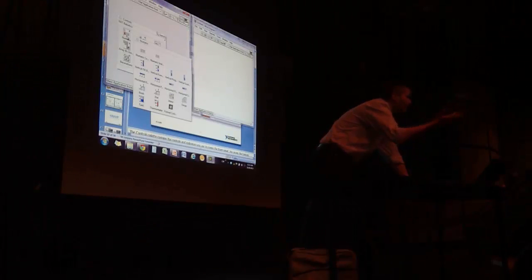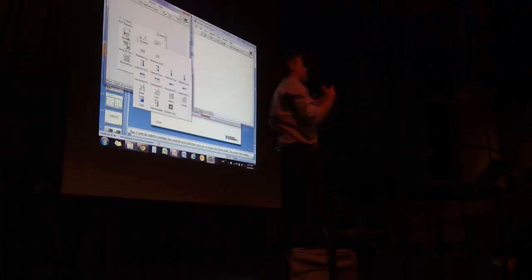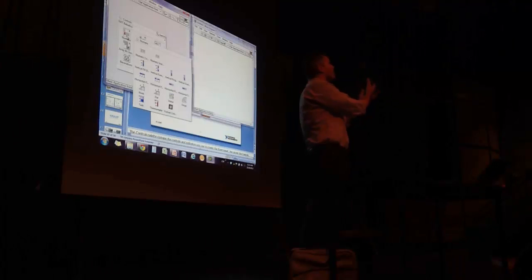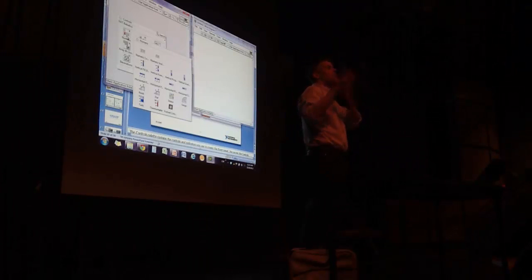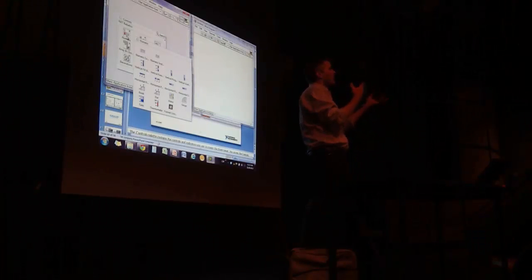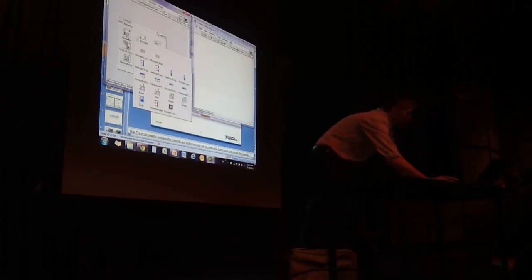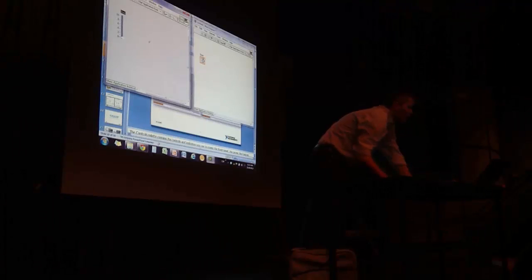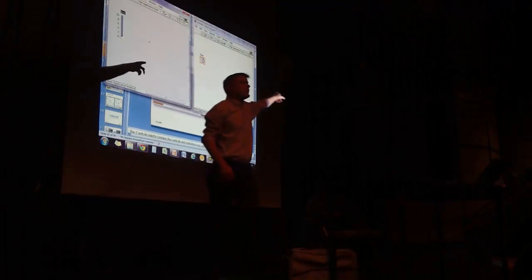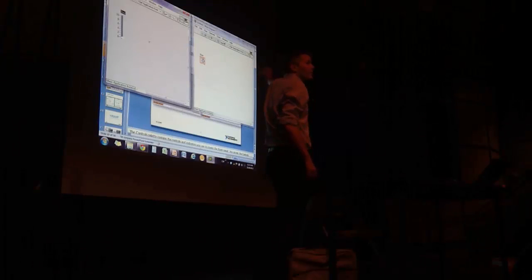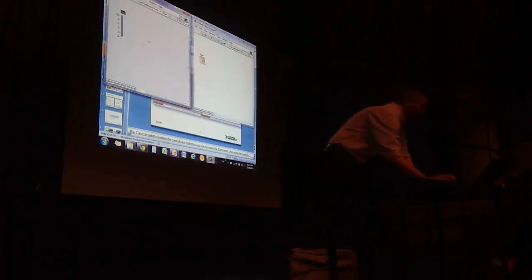So what you see here is a lot of different controls and indicators. The idea behind them is that with controls, you can put in a value, and with an indicator, you're displaying something. That's a very important concept in LabView, and it's even more important when you go to the programming side. I can just drop down one of those controls, and directly in the block diagram a terminal appears. This allows me to access the data of the front panel very easily.